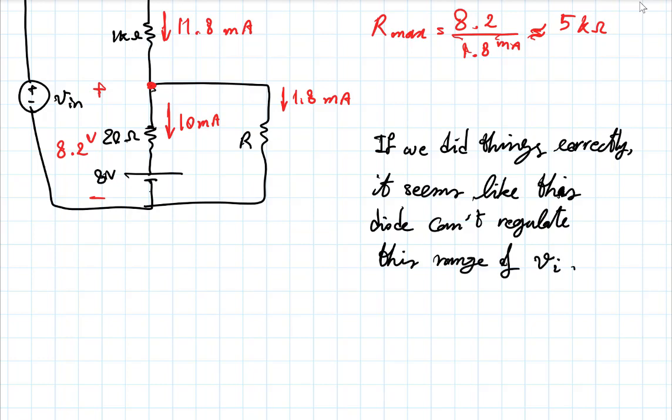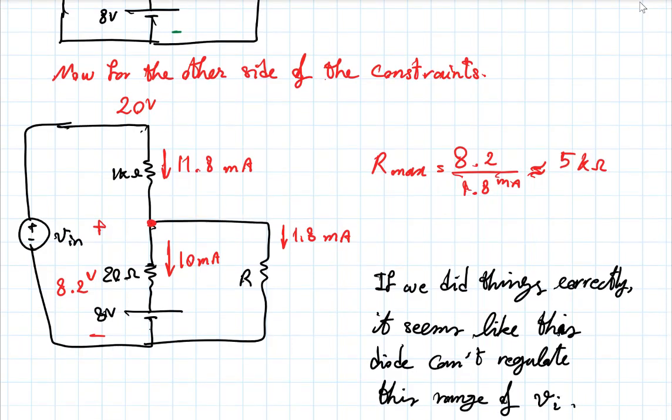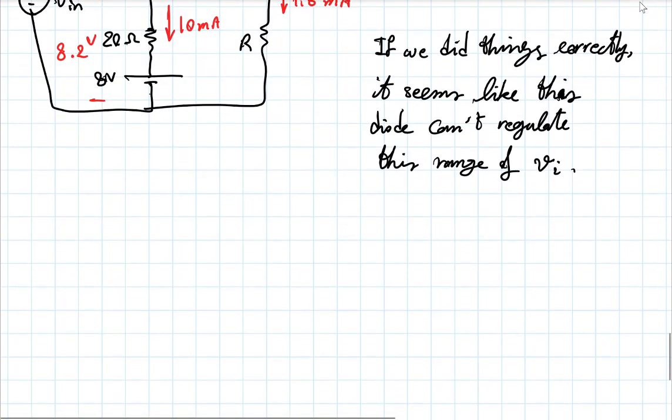So, remember the previous stage that you had built. For instance, it might have been a filtered rectifier. Well, make something that does not have a ripple going between 10 and 20 volts. If it was between 10 and 11 volts, maybe it would have worked. Alternatively, maybe you need a more forgiving diode. So think about the different ways in which you might make this work.